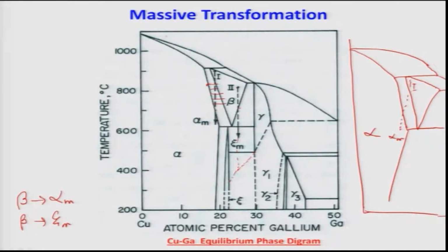As you clearly see, these transformations are very common in these alloys, and they have been observed. The reason they were observed was, again, serendipity: some scientists wanted to quench these alloys from high temperature, but did not quench sufficiently fast to form martensite.